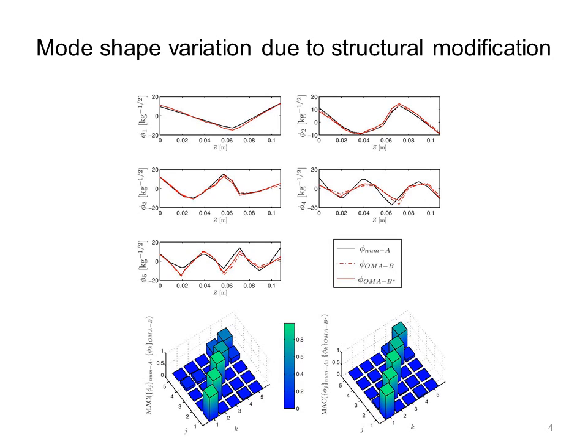The method proposed in this study gives significantly better results than the experimental modal analysis, especially at low frequencies, and is simpler to use since the measurement of the excitation force is not needed. It can be used on any similar small and light structure.